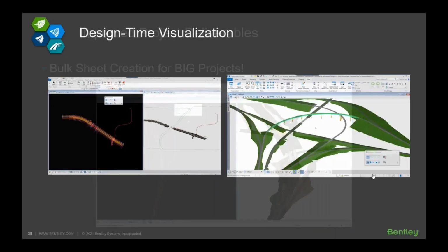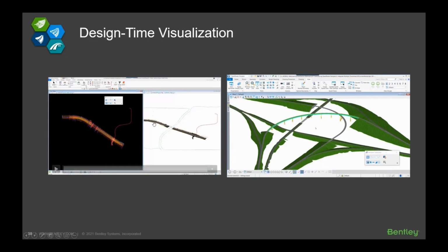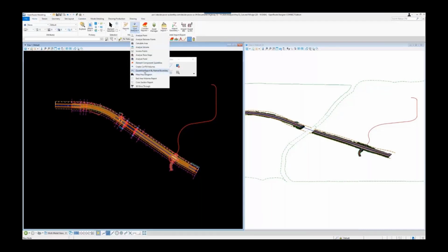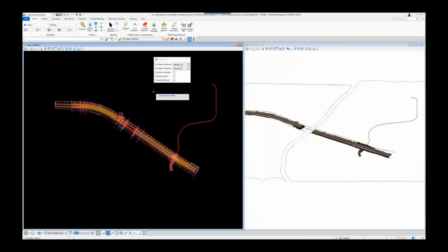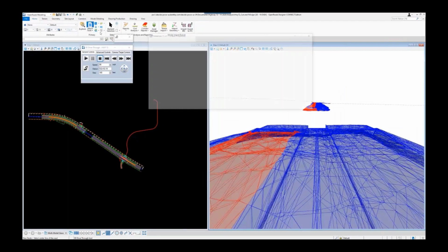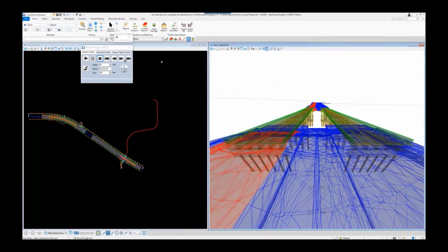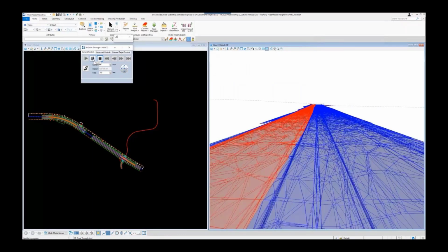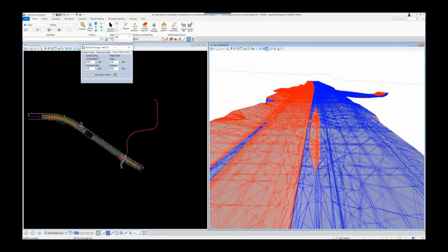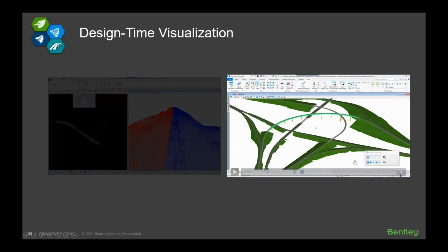Okay. Then lastly, before I show some samples of our users with OpenRoads Designer, the model that you create itself is, as I said, I have one example already shown, but I would like to reiterate that the model you create is the visualization model already, okay? By using this drive-through tool or 3D drive-through tool, you'll be able to visually examine your model. And then you can also use some ORD tools that allow you to record this as an animation, or maybe do a rendered still image or high resolution still image of the project that you have.